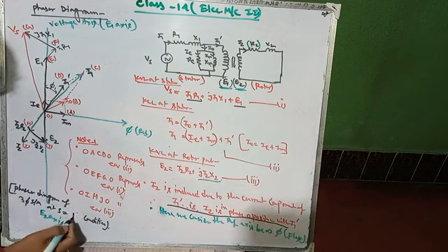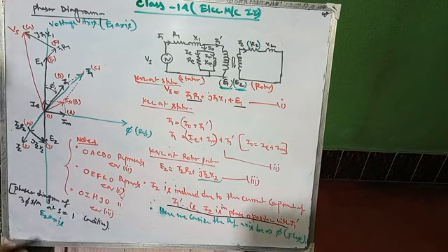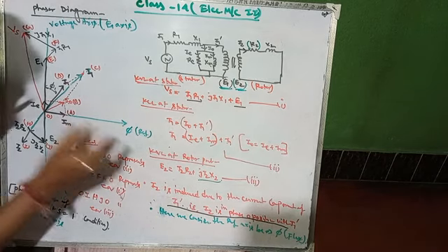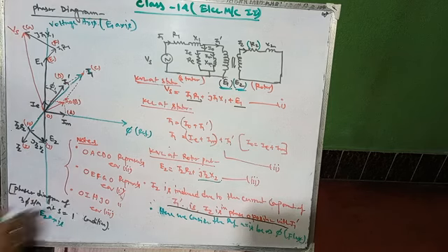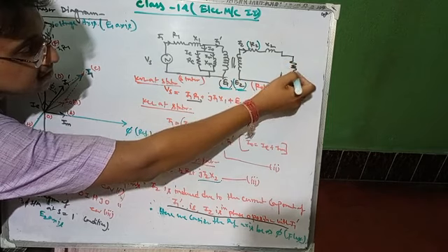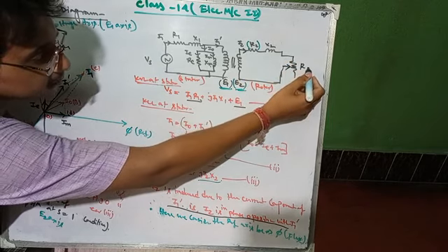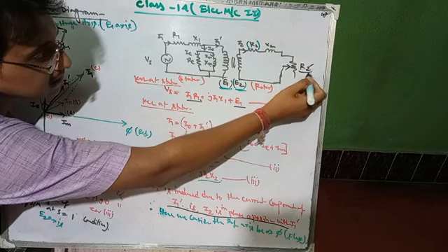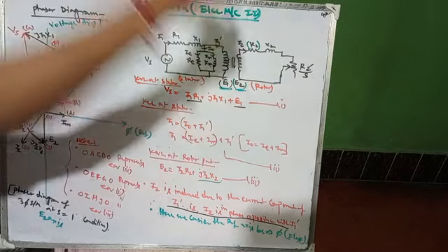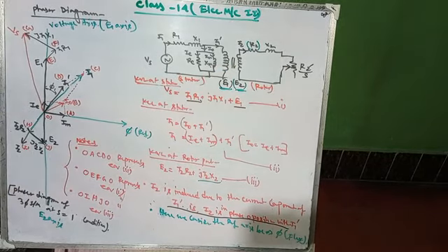No, S equals 1 condition, that is the standstill condition. Yes, right, it is a standstill condition. Now if we move to the running condition, when it is running with some particular slip, then there will be a resistance, and it is a variable resistance. As the slip is, so it is R2 dash by S. As the slip is falling, so it will be cutting, right? It will be cutting.